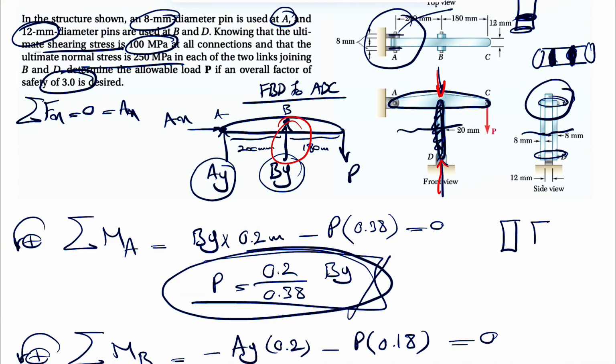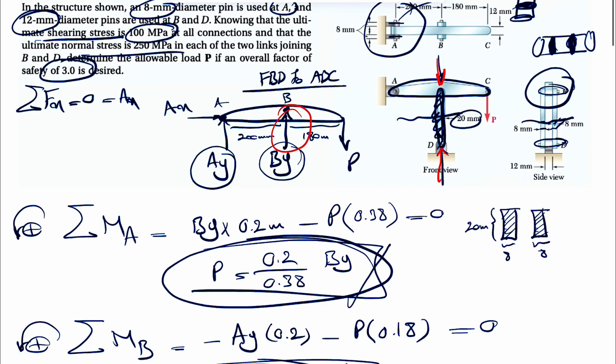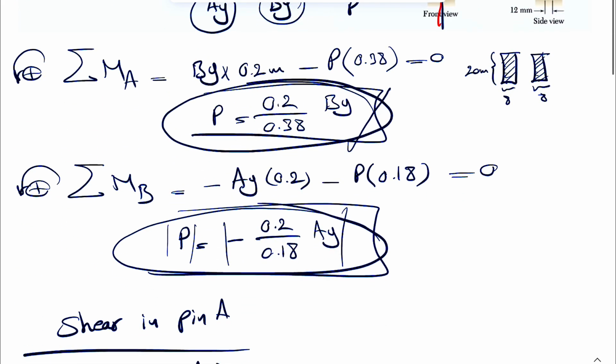And again, as we can see, we'll cross it into two links. And what we are dealing with is two different rectangles, 1 and 2. And if we want to find the dimensions, as we can see, the thickness in here is 8. And since it's 3D, it will be something like that in here. And the other side would be the 20 millimeter that we can see in the front view. So 20 millimeter. So for the area, basically we have 2 times 8 times 20.